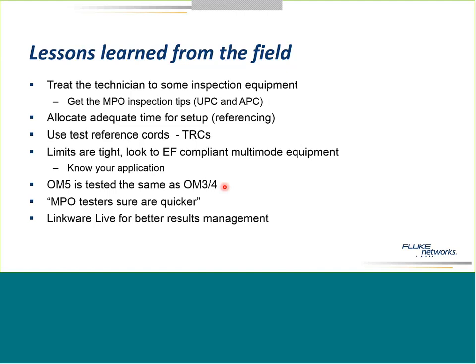What OM5 is giving us is the possibility to work at 4 different wavelengths, 4 different windows, if you will. I like calling them 4 different colors, a color we can't quite describe. And each one of those colors can transmit today 10 gig. So a single OM5 fiber could transmit today with the right transceivers 40 gig and receive 40 gig on the other fiber. Down the road, probably do more.